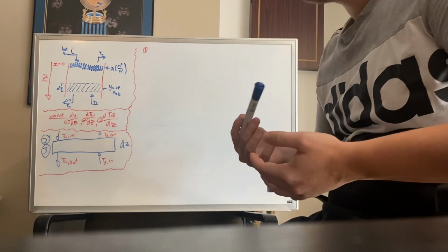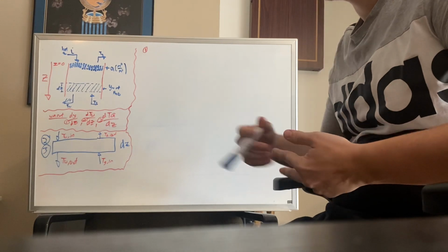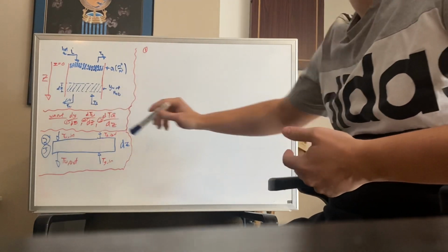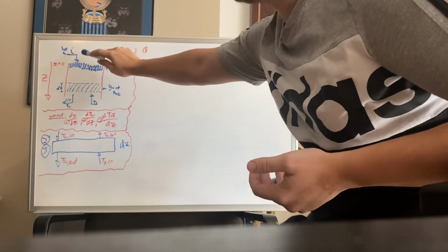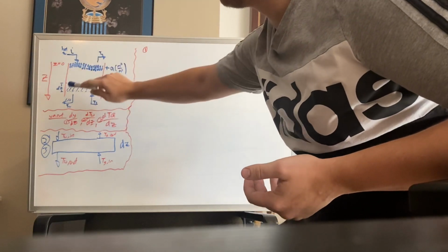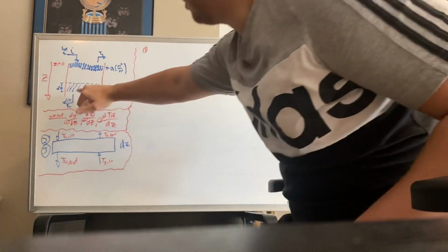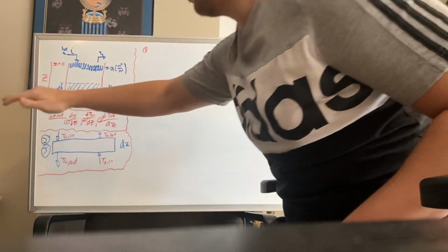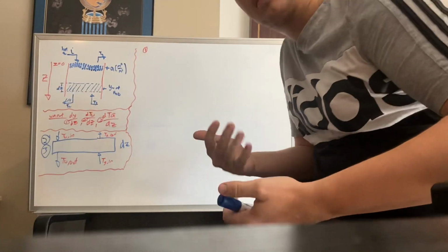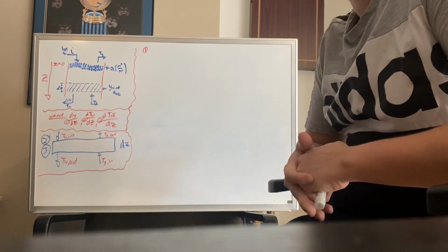So in this part of the exam, we will be going on to something a little different, where we will be looking at a cooling tower that has airflow going in and up it, and hot water going in at a liquid flow rate of L, down through the packing material of specific area A, and down to a point that's cold water at the bottom. The Z goes down into negative in the lower direction, which is going to end up causing it to be negative when we start developing our equations.